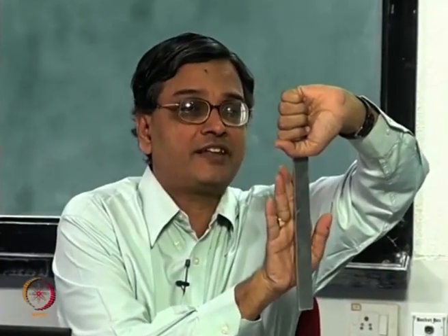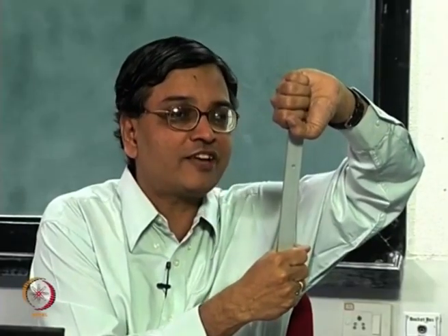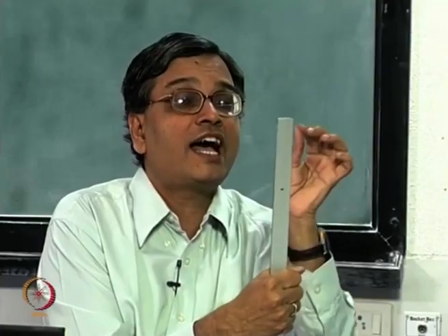And compare, I have an axial member, I pull it, I can do it by strength of materials, but the same axial member, suppose I have a hole, I cannot solve it by strength of materials, I have to depend on theory of elasticity. Even in theory of elasticity, the hole should be as small as possible, okay.